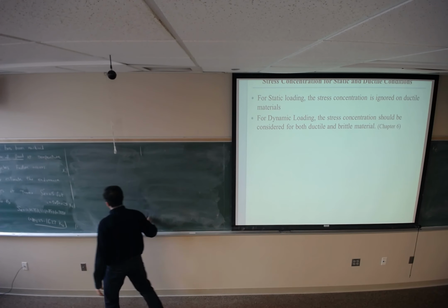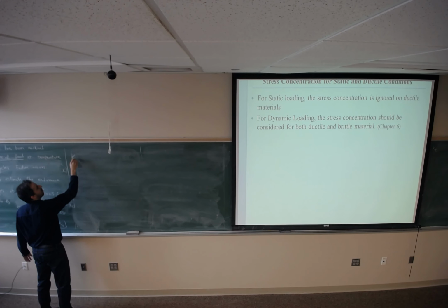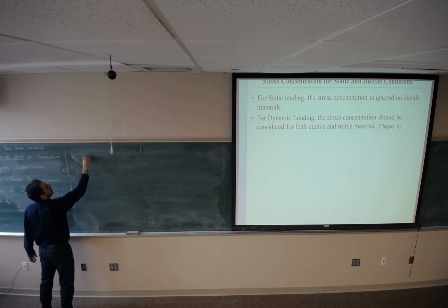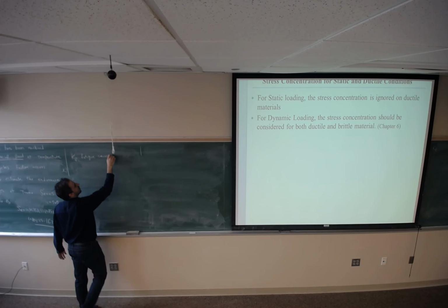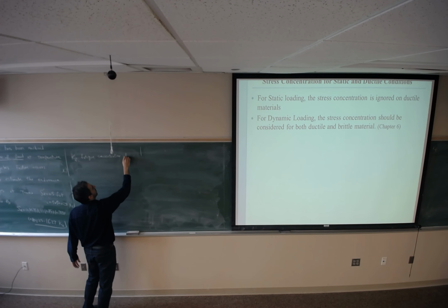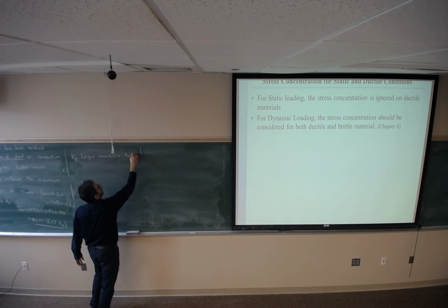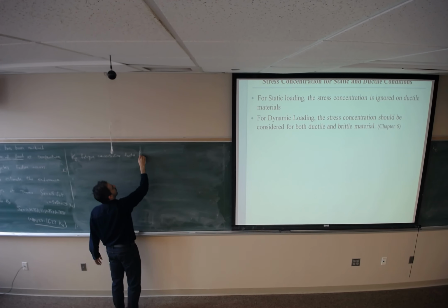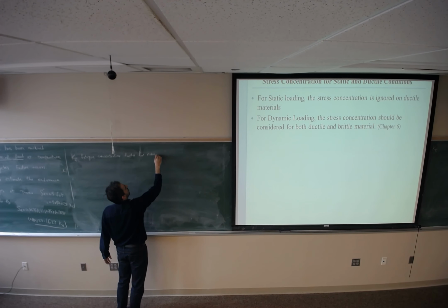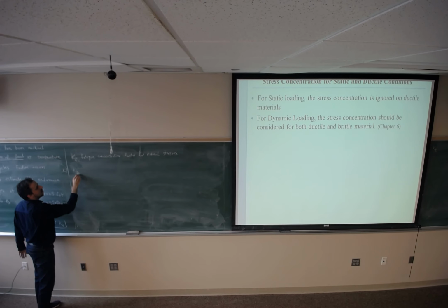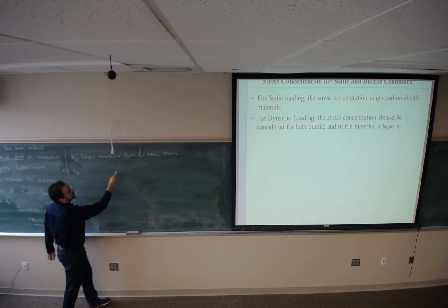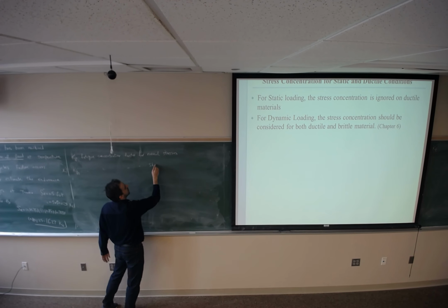I define two factors: KF, fatigue concentration factor for normal stress, and KFS, S representing shear stress, so fatigue concentration factor for shear stress.